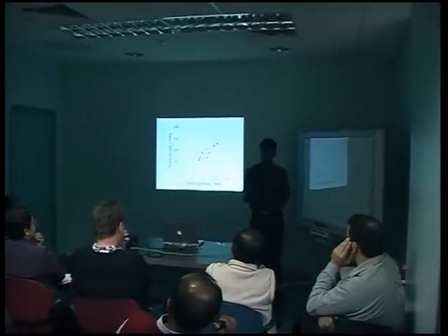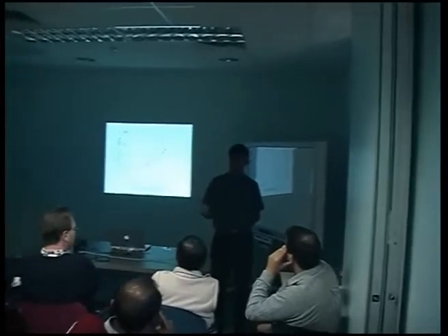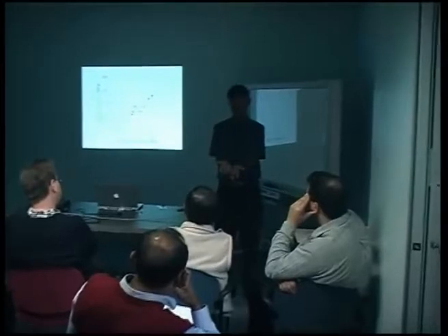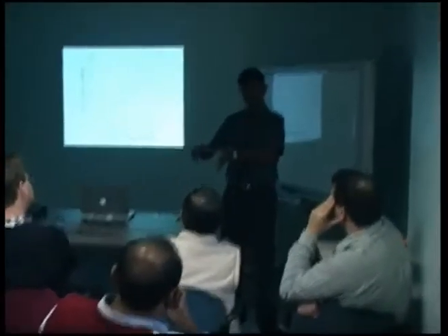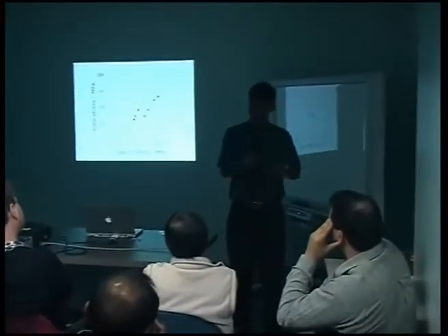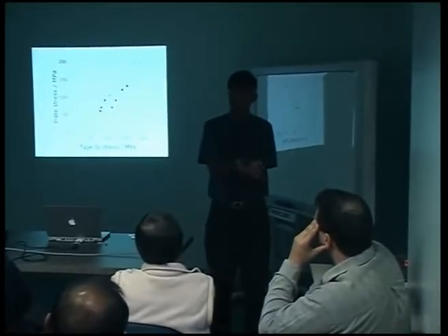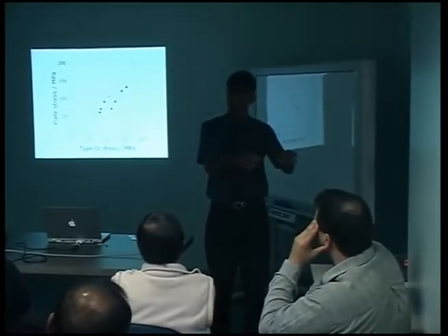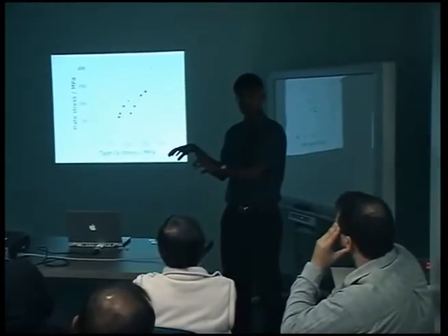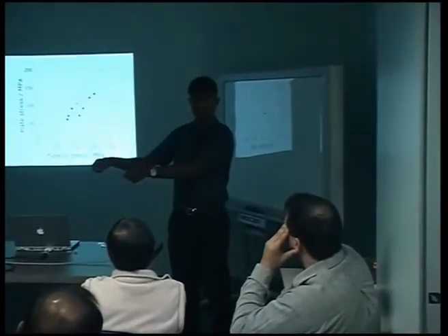That's an excellent point, you see, because some of these mechanistic models that we have take a huge amount of computer time to run. So supposing you want to control the whirlpool shape, you have equipment which can monitor the whirlpool and adjust the current, etc. to get the right shape. Now there are computer models for a whirlpool shape, but they might take several weeks to reach an answer. So what you could do is run those computer models, get the output from that, then train a neural network, which once it's trained will take milliseconds to run, so you can use it for online control.